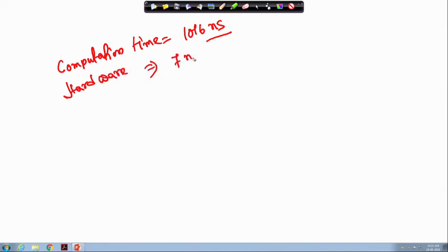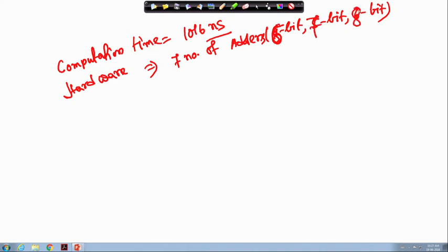Then the hardware requirement is 7 adders, not all of them 4 bit. The first stage will be 4 bit, in the next stage it requires 5 bit, and in the next stage it requires 6 bit. So, why I need to do that, I will note later. So, it will consider 4, 5, 6, 7, and this will require 8 bit.